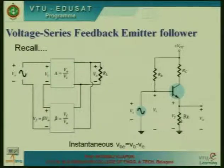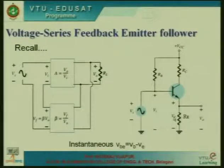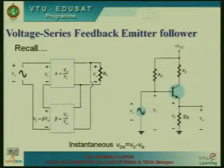Previously, in the stability analysis in the earlier chapters, we discussed that Re provides stability. We have seen that Re protects the Q point against variations in temperature. Now here it is playing a major role; its role in providing stability against temperature is analyzed from the feedback point of view. So, this is the circuitry. How does the circuitry work here? How can you have a feedback which ensures stability?